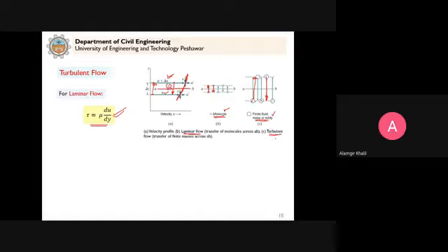So in case of turbulent flow, transfer of finite masses across AB occurs, rather than molecules. So this is how the transfer of momentum occurs. And as a result of this, on this AB line in turbulent flow, the shear stress will be generated as shown here. So there will be a shear stress.